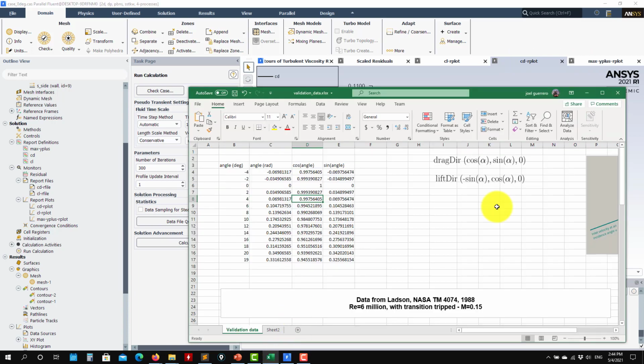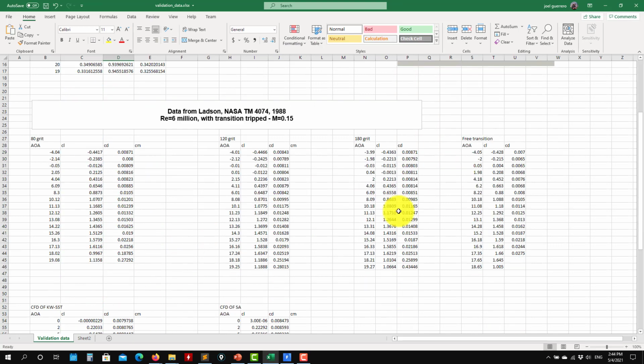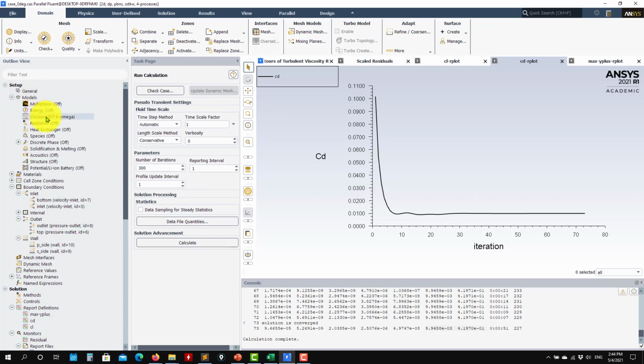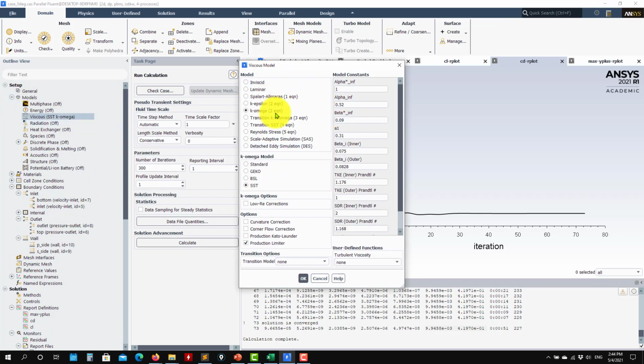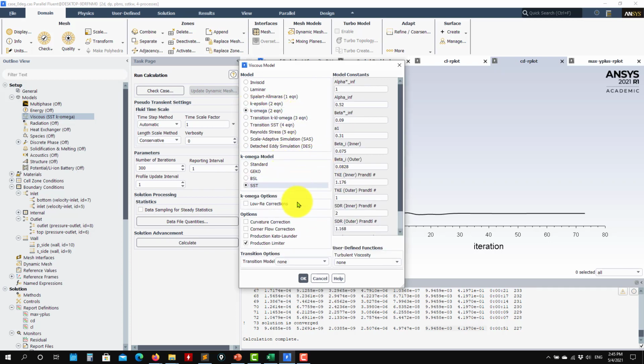I really love these cases because here you can spend the whole week validating and testing different turbulence models. In this case, we use the K omega. Like in the previous case, you can now go to K epsilon and try all the combinations, and see the influence of using every different K epsilon variant with different wall function formulation. See that for K epsilon you need to specify the near wall treatment. K omega is Y plus insensitive.